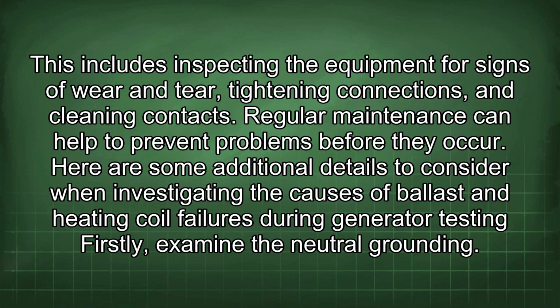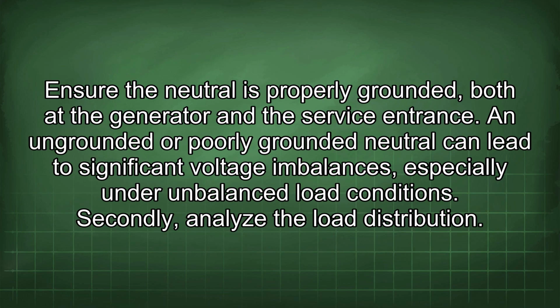Firstly, examine the neutral grounding. Ensure the neutral is properly grounded both at the generator and the service entrance. An ungrounded or poorly grounded neutral can lead to significant voltage imbalances, especially under unbalanced load conditions.